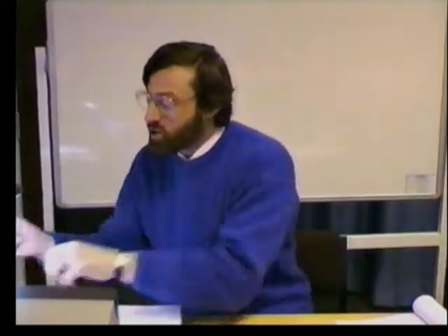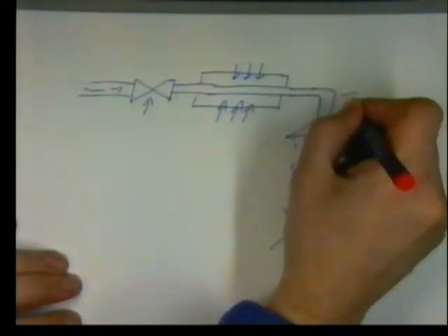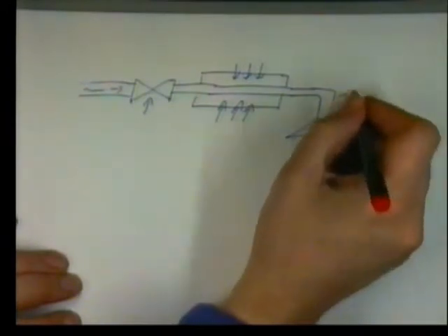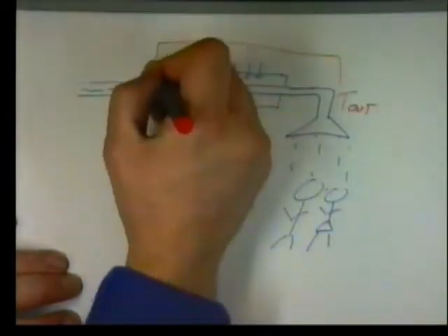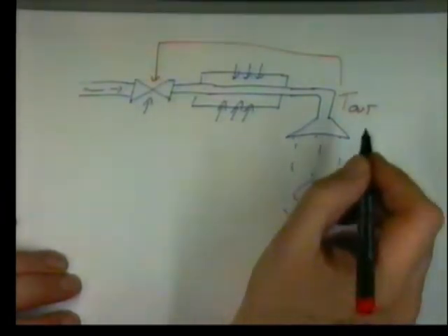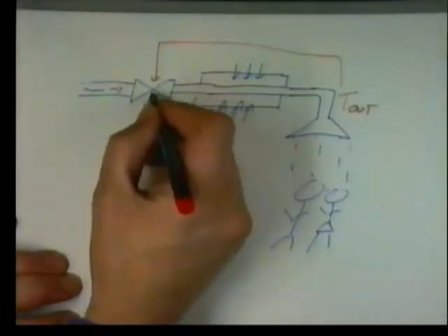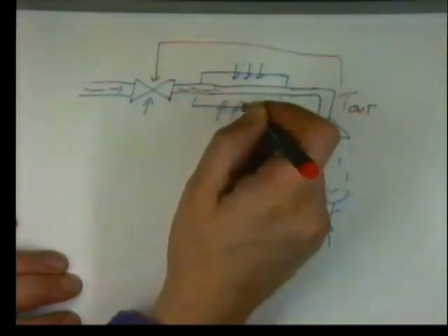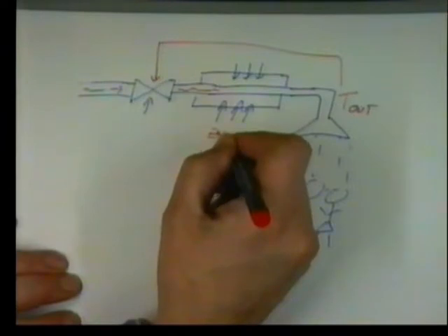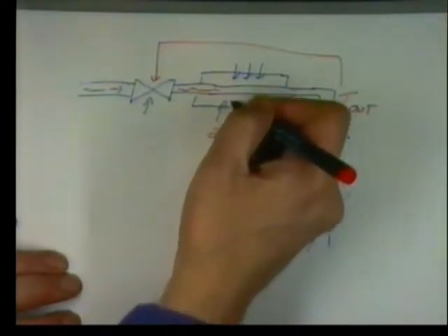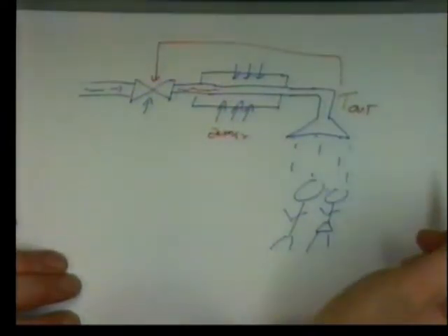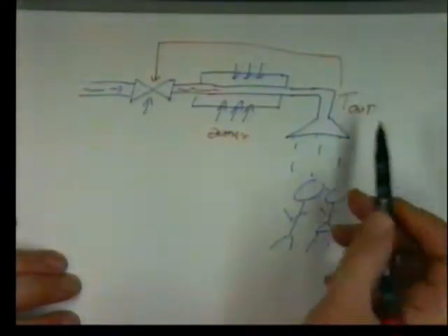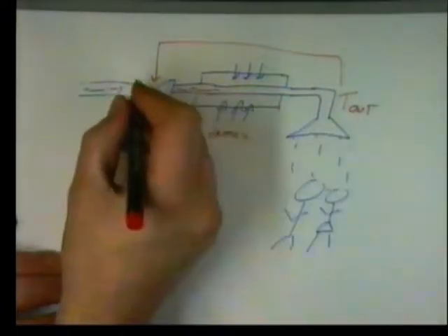So the way we control the temperature here, and let's call this temperature out, is by measuring the temperature out and controlling the water valve. If this was too cold, you would close the valve off, less water flows through because it's a fixed amount of energy going in. The temperature lift is greater, and so you get hotter water. Now you could develop very easily a feedback control system based on measuring the output temperature.